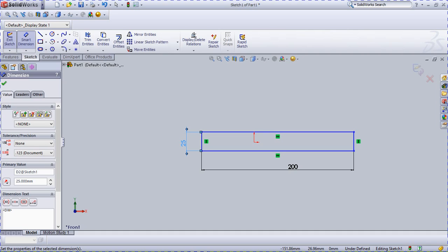So this bearing block not only bears the shaft and lets it rotate easily, and reduces the friction between the shaft and the mating parts, it should also be capable of carrying the load efficiently. That is why I have selected 25 mm thickness.